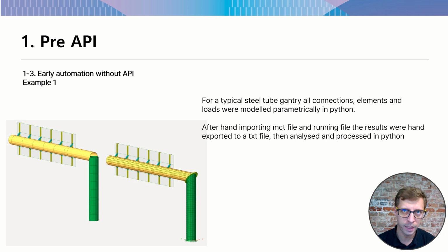Then the MCT file was generated. This had to be imported within MIDAS, the program run, and then everything exported by hand, all the tables generated. As a side note, just 2 models were generated, one with plate elements, one with beam elements, to then compare the 2 results.